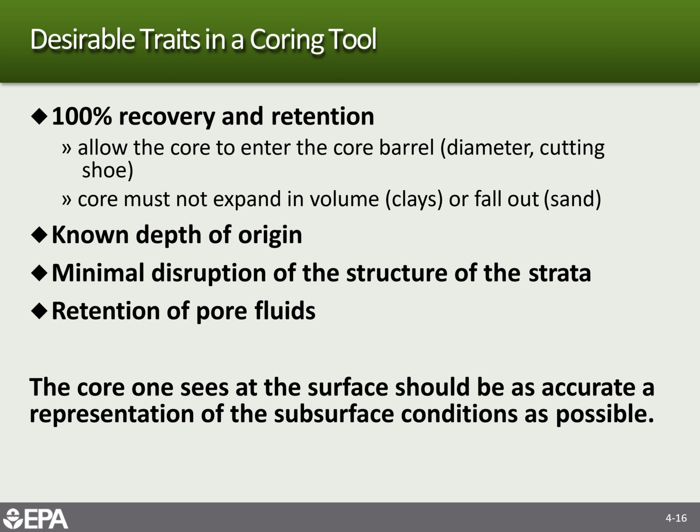You'd like the samples to have minimum disruption as you bring them to the surface, retaining the pore fluid, so that if you want to, you could sample them and send that off for analysis. The samples you see at the surface should be as close to subsurface conditions as possible. And no, I won't be reading all the slides.